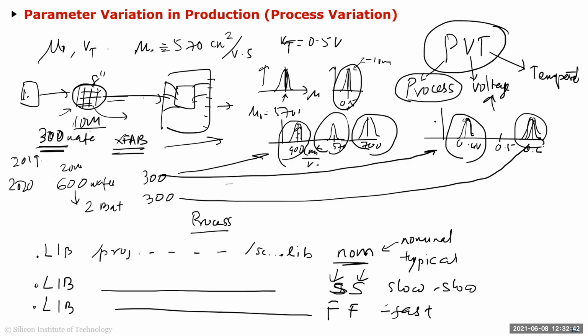Process is the part I just explained. You want to make sure for all corners, these are called process corners. Okay. So when people say, okay, is it working in the slow corner? That's what they mean. So all corners. So for process corners, you want to make sure that you're meeting the specifications of what your chip is supposed to meet. And then temperature, right?